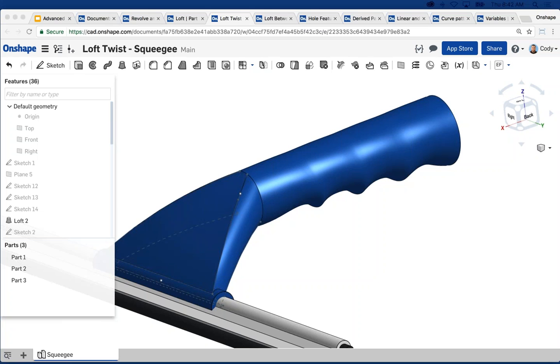Forgive me. Can we make splines symmetric in this case? No, it's important to point out each guide has independent control over each corner, so there's no way to define symmetry using one guide in this example. So in this example, you would need 4 independent guides.